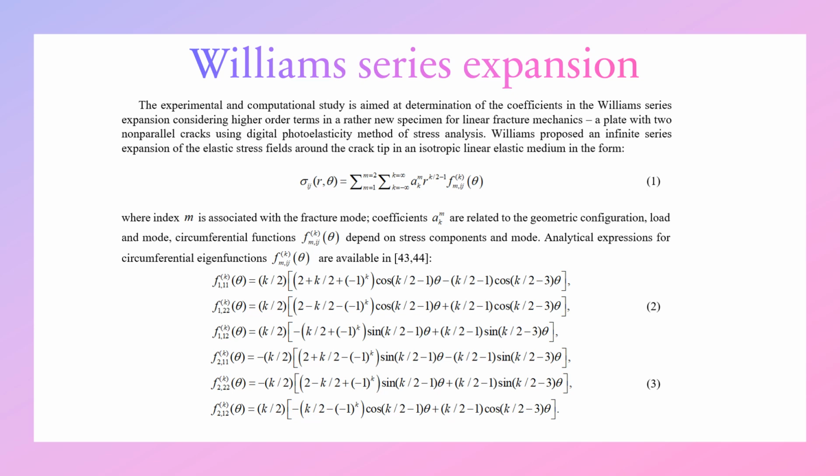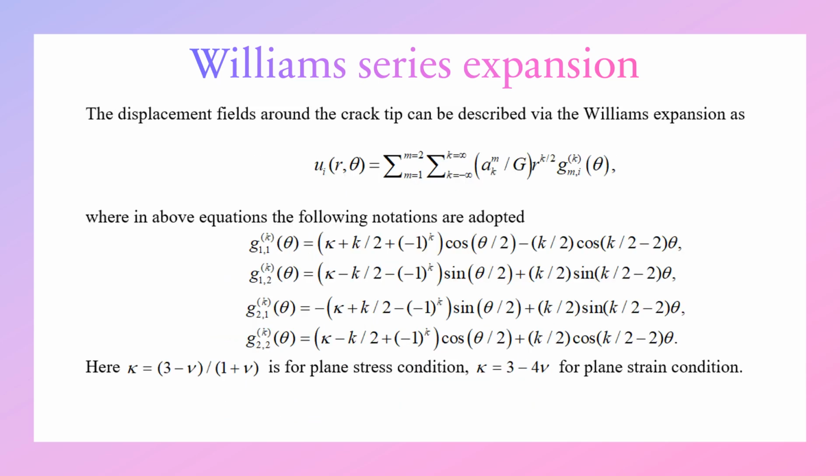The angular functions are well known, and we can present in the asymptotic form the displacement fields in the vicinity of the crack tip. And the main question is, how many terms we have to keep in this asymptotic presentation.